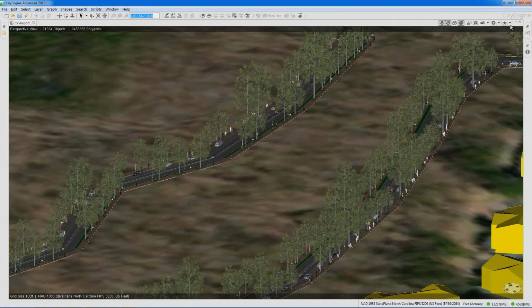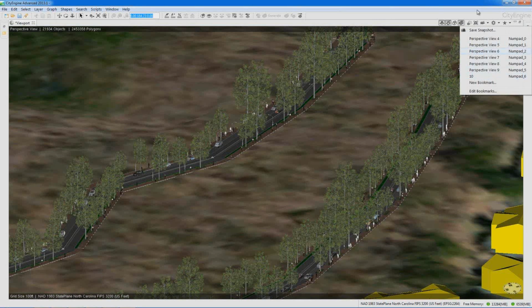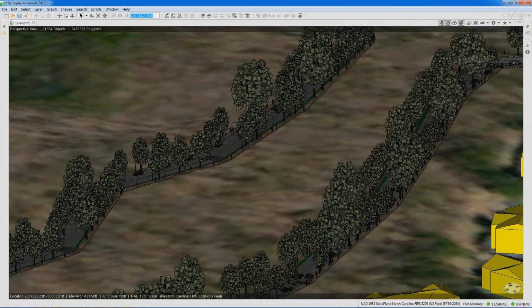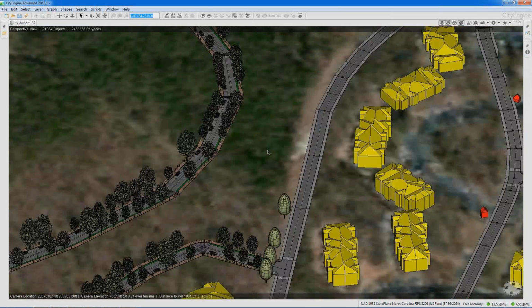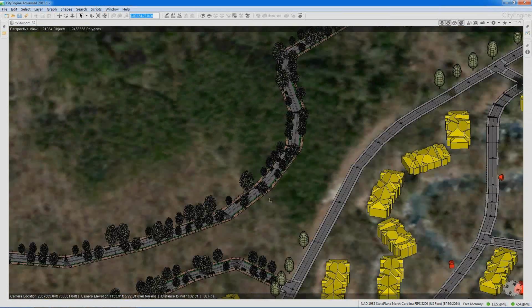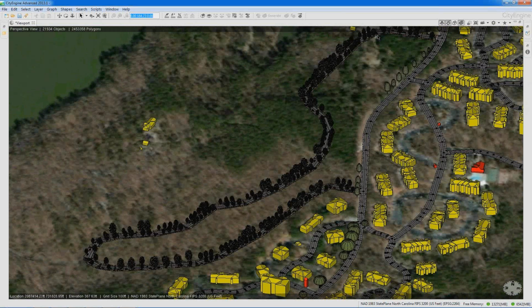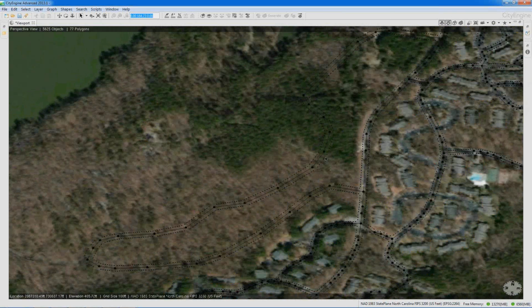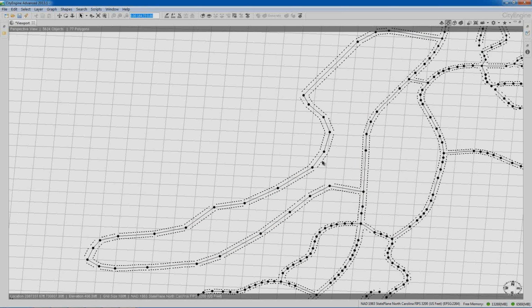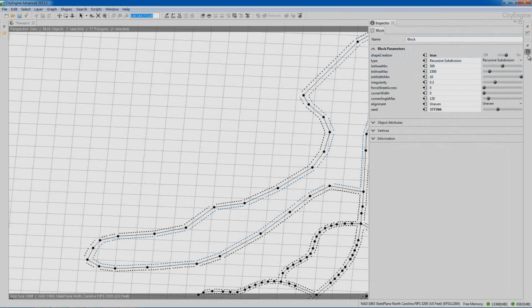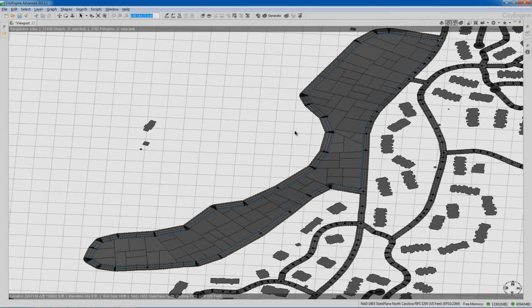So now that we've created the street networks, the next step, taking a step back a second ago, we were going to subdivide parcels. Let's do that now. So I'm going to select the center lines between where the street networks exist. So let's turn off the shapes and just select the center line. I'm going to turn on the parcel subdivision capability here. Turn the parcels back on.